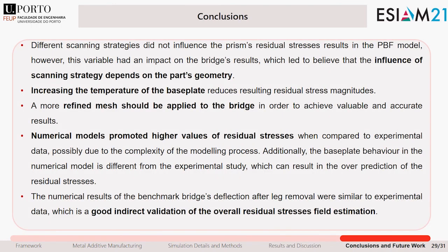Well, regarding the conclusions of this work, different scanning strategies did not influence the prism's residual stresses results in the powder bed fusion model. However, this variable had an impact on the bridge's results, which led us to believe that the influence of the scanning strategy depends on the part geometry. Increasing the temperature of the base plate reduces the resulting residual stresses magnitudes. A more refined mesh should be applied to the bridge in order to achieve valuable and accurate results.